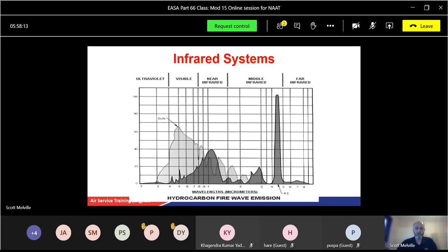Radiation emitted from fire crosses the airspace between the fire and the detector and goes through a window on the detector, and the window will analyse the broad spectrum of light. For example, the filter only allows radiation in a tight waveband, centred around about 4.3 micrometers. So we look at the radiation: obviously, the more intensity, the greater the heat, and the greater the heat, the better the chance of a fire. Again, all these voltages will be processed and sent up to set off the alarm.